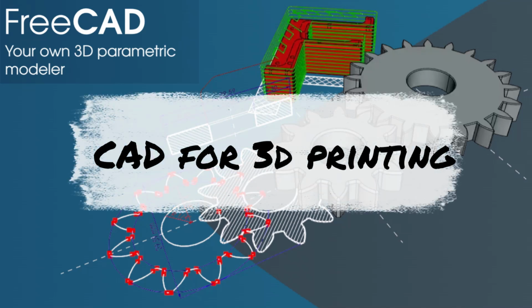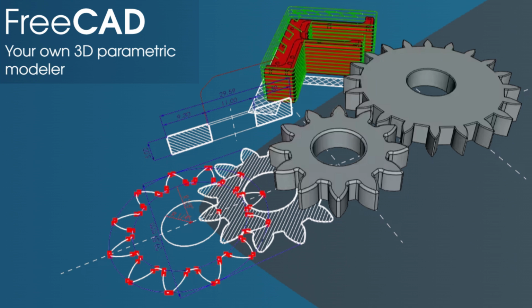This is a little different video than what I usually post, but I had some time to play around with FreeCAD and decided to put together a little example of how I model stuff in FreeCAD so that when I 3D print the parts, they will fit correctly. And also a way to easily modify the tolerances of the part when I go to print it.